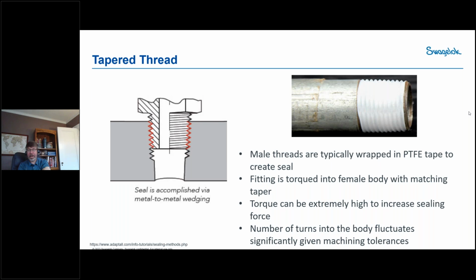It's a very long path, so that's good, but the Teflon will permeate, so gases will flow through the Teflon tape and eventually get to the outside. Again, it's a long path, but it will reach the outside. This is not well supported really with vibration, but because the Teflon tape seals throughout that entire length, there is no real dead space that will create a corrosion entrapment area.